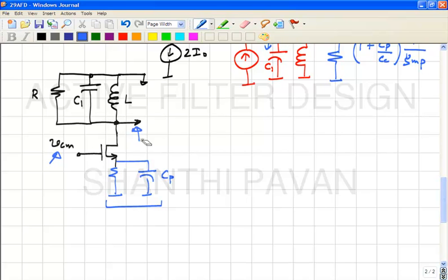And let me reiterate again, at the risk of sounding boring, this incremental circuit is used, or should be used, to relate what to what? Changes in the input common mode voltage to changes in the output common mode voltage. Why I am emphasizing this so much will be apparent the moment you take a look at a differential pair.